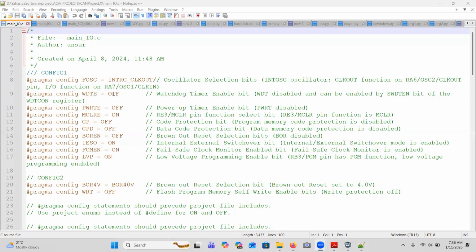We are turning it off. We are not using the timer as a watchdog timer, so there won't be any watchdog timer operation. I think we have studied the watchdog timer, which is used to reset the microcontroller when something hangs. Usually people load it with some value after some programming line, and if again they reset it. Like that they used to do.